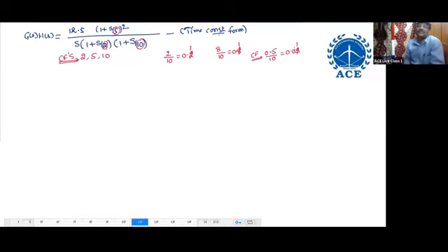Starting frequency, initial magnitude: at what frequency do you have to calculate the initial magnitude? One decade below, one decade lower than the first corner frequency, and it should start with 1. It is just a standard representation, that's all. So here the first corner is 2, sir; I will start with 1, I will start with 0.01. So it means below 2, anywhere we can start.